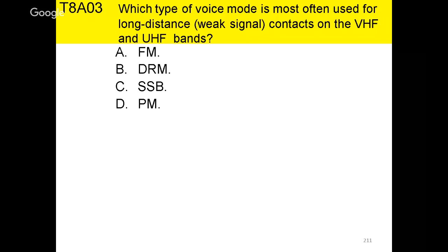And if you're familiar with CB, it came out initially as AM radios. They had 23 channels. They eventually went to 40 channels. And then when they brought out single sideband capability on these radios, the manufacturers were advertising, "Oh, look at this. It's not a 40 channel radio. It's a 120 channel radio." Well, that was kind of a misnomer. But in a way, it did have, if you wanted to count it that way, 120 channels.